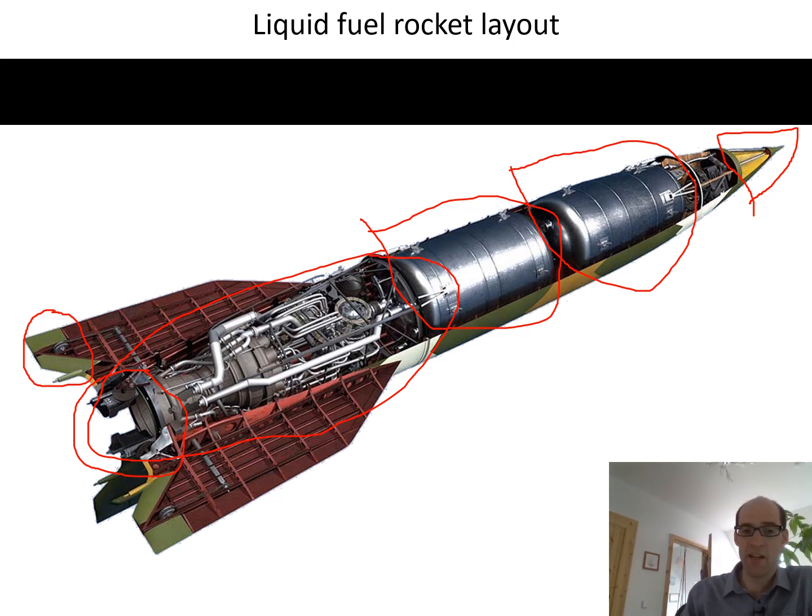The fins in the rocket exhaust obviously detract from the flow of the rocket, and the graphite can wear out due to the high temperatures involved. Another difference with the V2 versus many modern rockets is the turbo pumps were driven by a separate chemical reaction. I can't remember the exact form of chemical, but it was expanded over a catalyst which created steam, and that drove the turbo pumps independently of the main fuel supply.